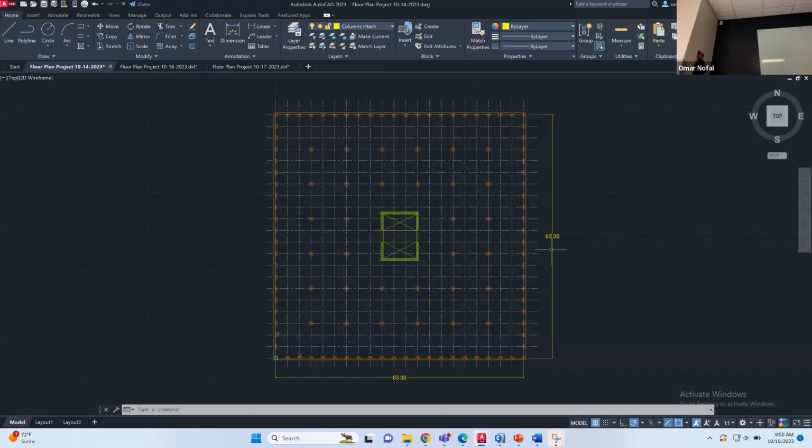If you remember how we draw these models on ETABS, we need to export the columns as a polyline, closed, not single lines. Can you see this rectangle? All these lines need to be connected together. If it's a regular line, like broken lines, ETABS is not gonna see them. But if they are a polyline, it means they are connected, and ETABS is gonna see them, okay? So this is one thing. And make sure they are not blocked. If you make an AutoCAD block, ETABS is not gonna see them. That's one thing.